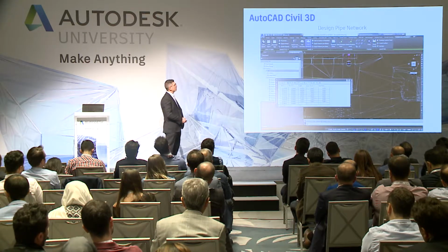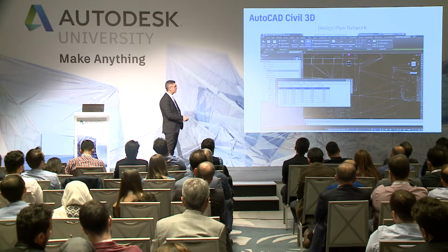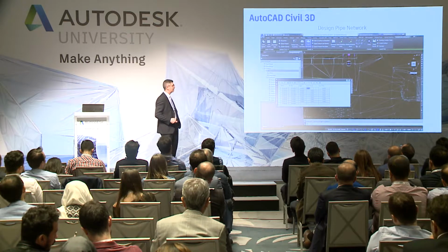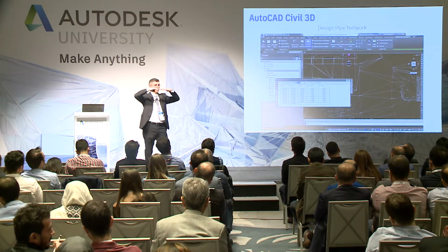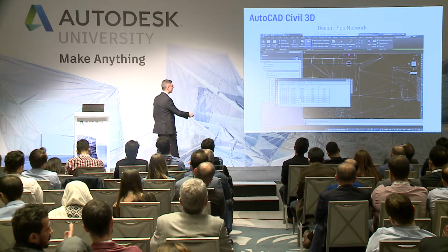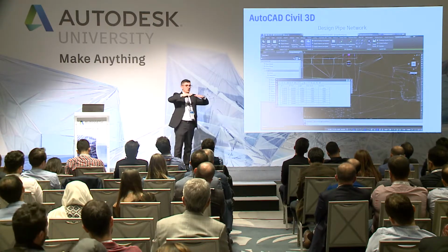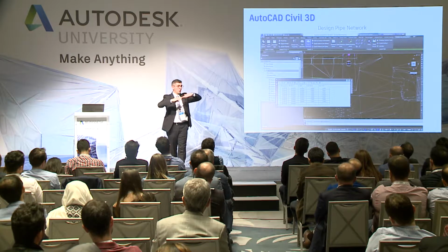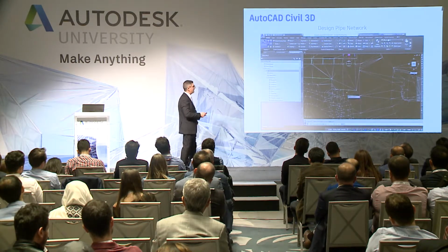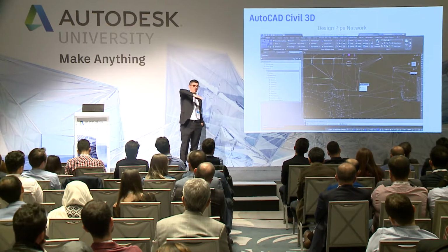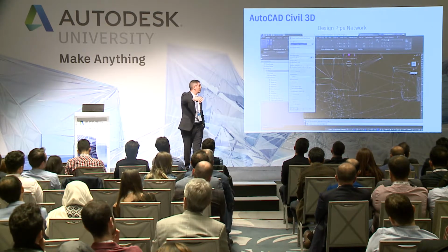In the conversion, I need to set the elevation. I already told you that it's flat, but for the sewage system, it's not good that the slope is flat. Then in this window, I need to set 1% of slope for my sewage system dynamically, and then my alignment has a little bit of slope from the starting point to the end point.